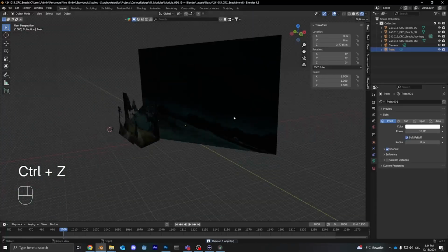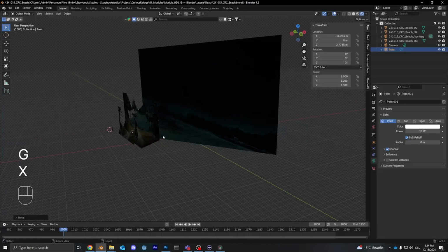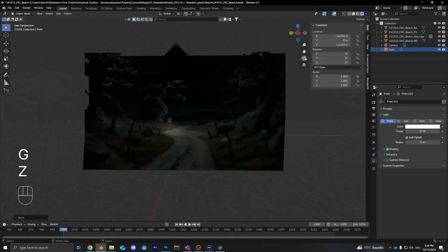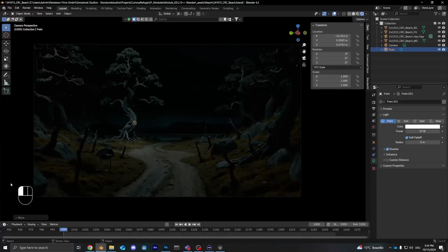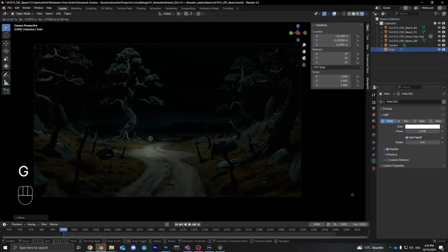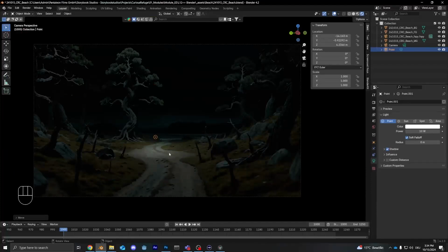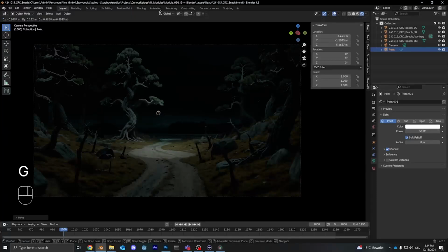And now we want to move this point way further here, so we actually have it in our scene. And you'll see, because we have the Principled BSDF, the scene will actually react to our light, which is kind of cool. Except here on this little transition. Because the scene is quite large, though, we're going to want to increase this light if we want to have a real effect on it.